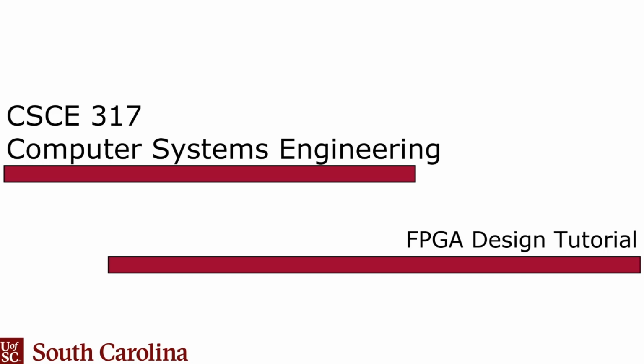We bought them for this class, but we bought them for flashing the firmware, not for debugging. The board had the soldered capacitor, and we never figured out a way to take that capacitor off, so there was no way to actually use the debugger. So with the FPGA boards, we have full debug support, so that's why I decided to switch.